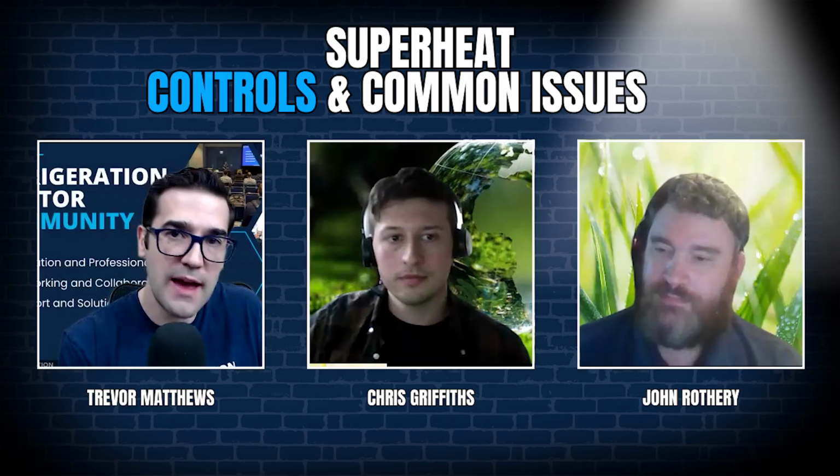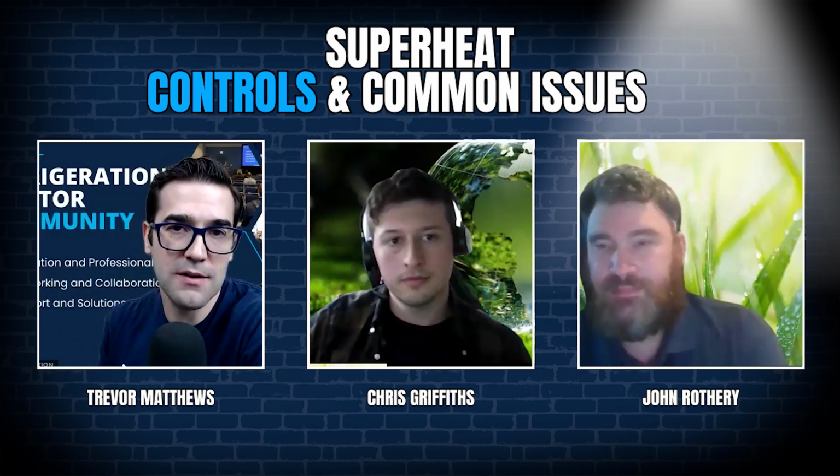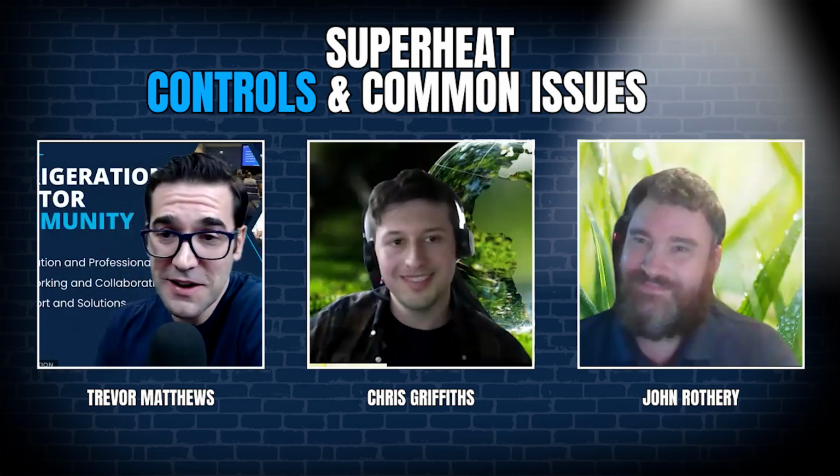But when you understand the design side, you can actually go in and plug stuff in very quickly. At first I thought, okay, how do I size these 4 compressors for this capacity? And then all of a sudden I plot it out and I'm like, okay, this makes sense now. This is my total heat of rejection. This is why I have this. This is my discharge, what it should be. And then you plot that inside the different software like the Bitzer or the Bock or the Danfoss or the Copeland, whatever it is, and then you can see either the issues or how it works. Anyway, for me, design has definitely changed the game for CO2. That's for sure.